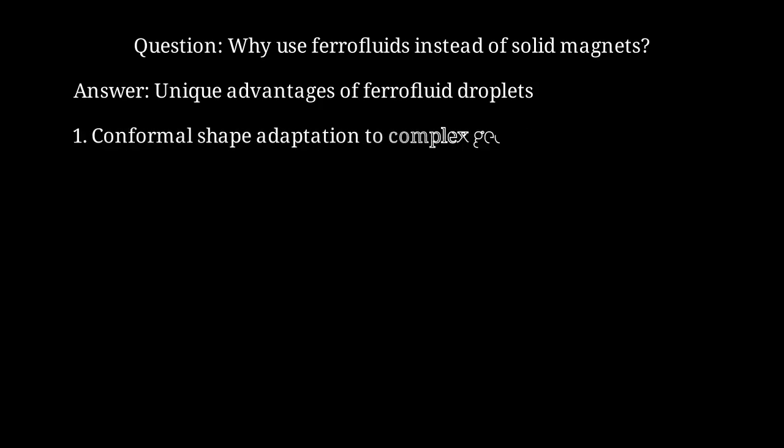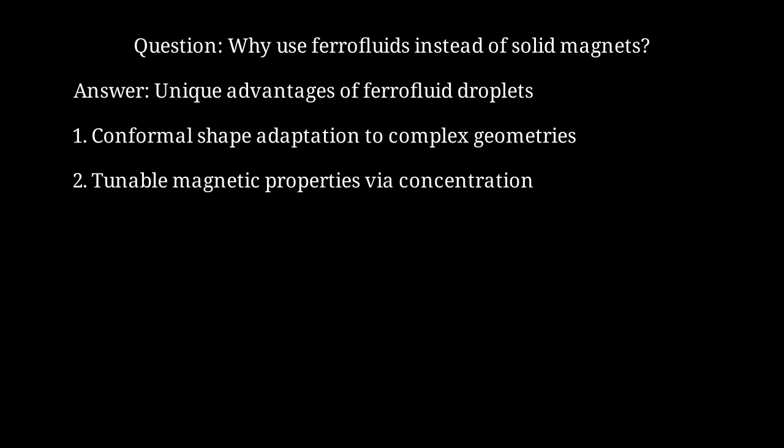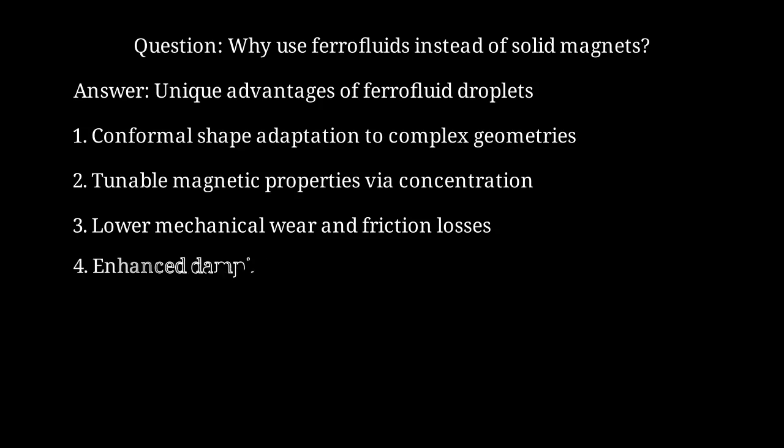First, ferrofluid droplets can conform to complex geometries. They're liquid, so they can fit into spaces where solid magnets cannot. Second, their magnetic properties are tunable. We can adjust the concentration of nanoparticles to optimize performance for specific applications. Third, being liquid, ferrofluids exhibit lower mechanical wear and reduced friction compared to solid magnets sliding in tubes or channels. Fourth, they provide enhanced damping characteristics, which is valuable for controlling resonance in oscillating systems.